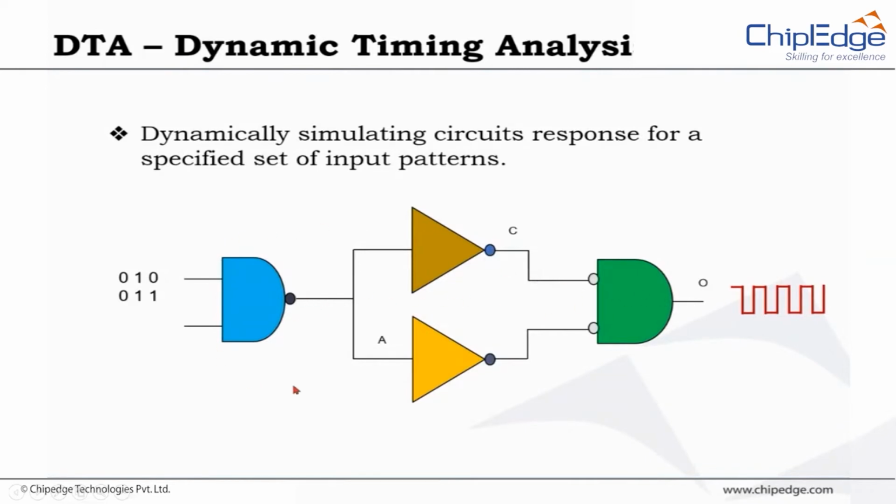When you run a simulation by passing patterns on the gate level netlist, the tool is going to come back and say there have been violations on hold, setup or whatever, depending on the constraints you have put in your network. So that is definitely a possibility. However, it is greatly limited by the ability to generate these patterns. And so dynamic timing analysis as a method of sign-off is an improbable aspect for us today.